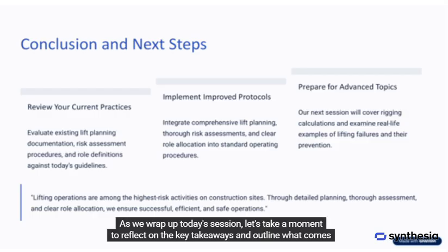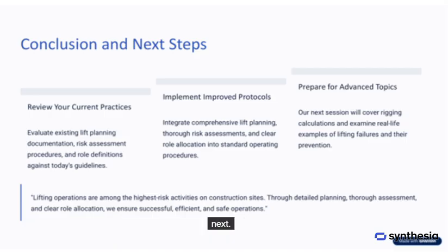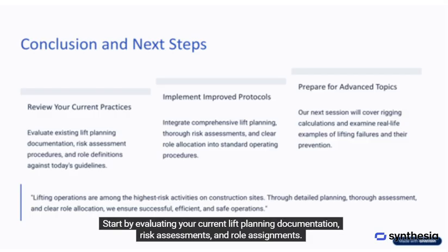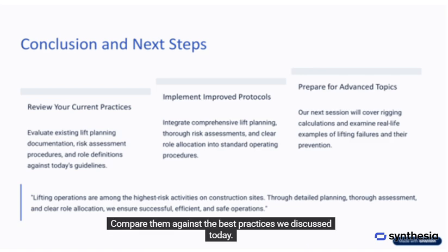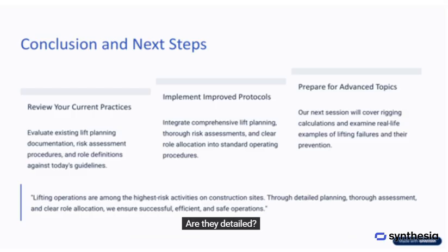As we wrap up today's session, let's take a moment to reflect on the key takeaways and outline what comes next. 1. Review your current practices. Start by evaluating your current lift planning documentation, risk assessments, and role assignments. Compare them against the best practices we discussed today. Are they detailed? Are they site-specific? Are they consistently followed?